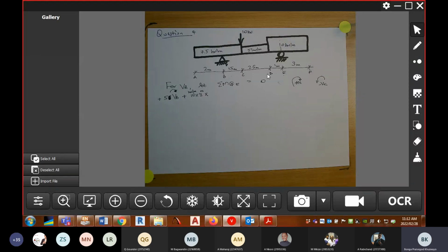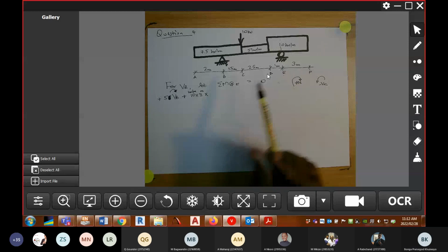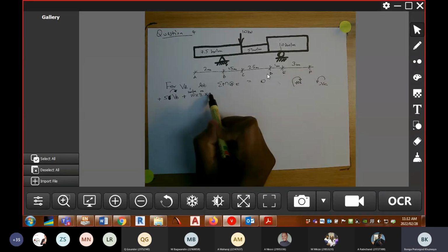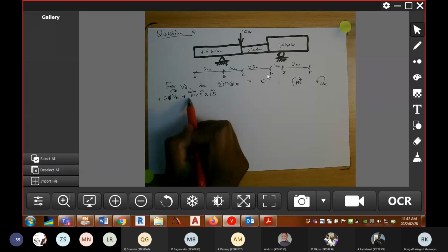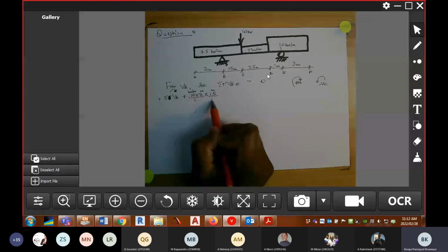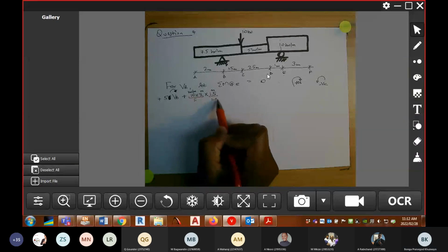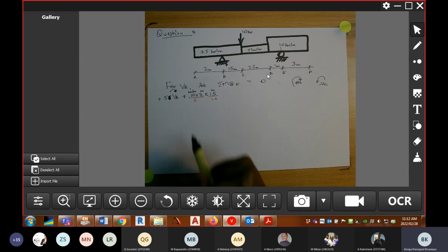And then the lever arm for that force is 3 divided by 2. 3 divided by 2 is 1,5. The unit there is meters. Right, so what we're saying is this is a force, and then this is a lever arm, the perpendicular distance.